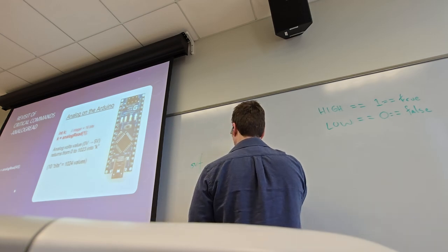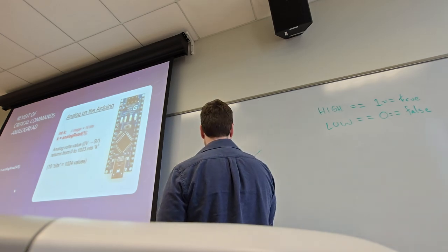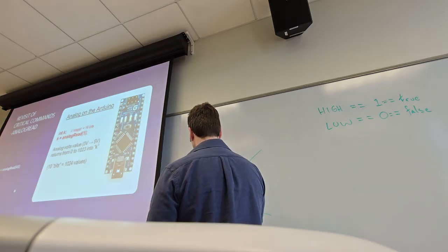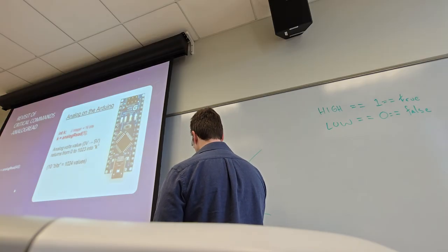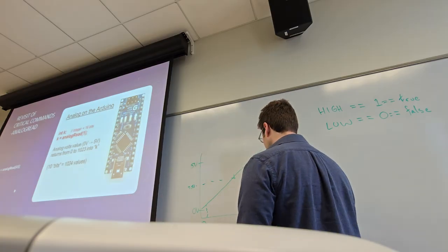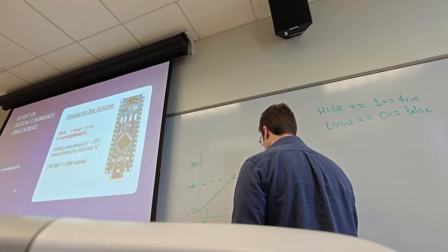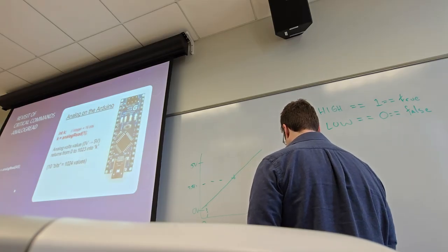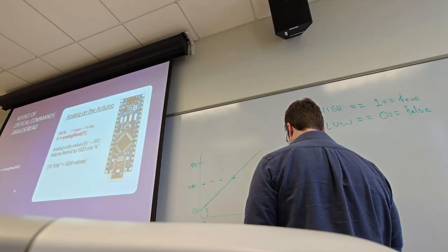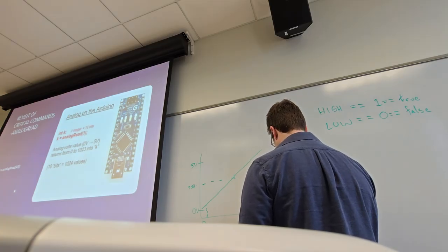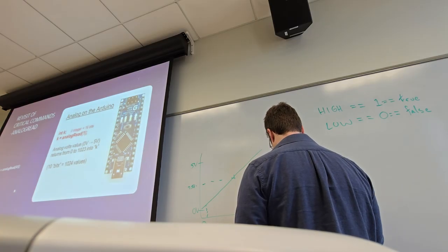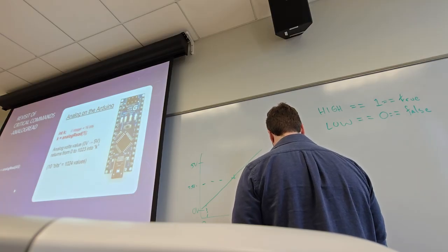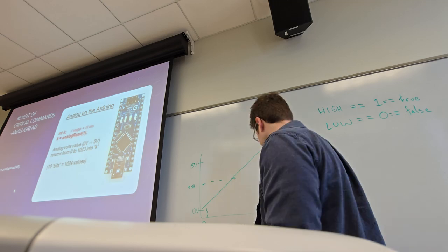What would be a linear scale from 0 volts to 5 volts, for example, halfway on that scale would be 2.5 volts, is mapped to a value between 0 and some maximum. For example, 255 or 1024 or 4096, for 8-bit, 10-bit, 12-bit, I believe.